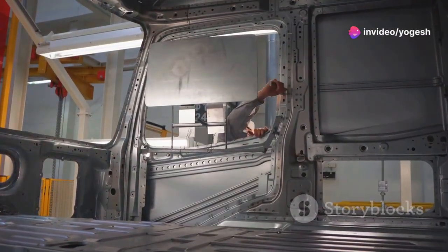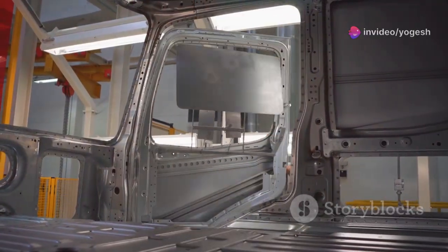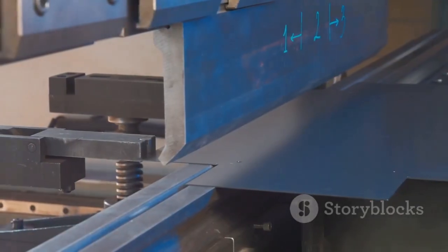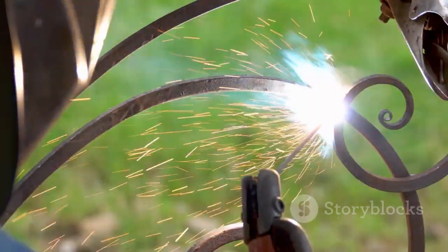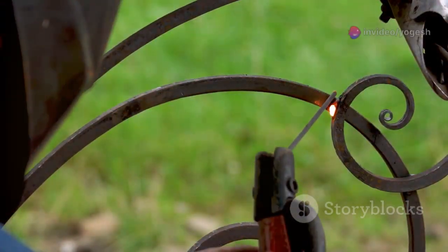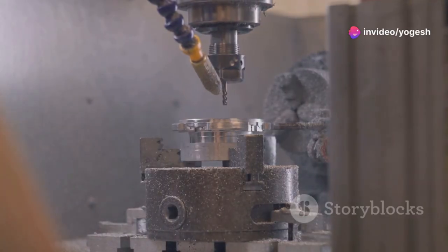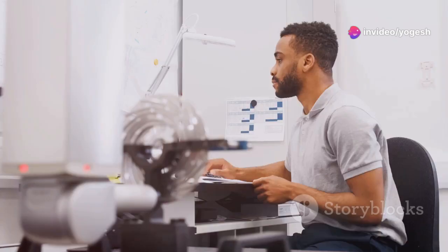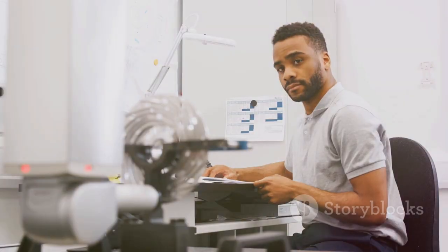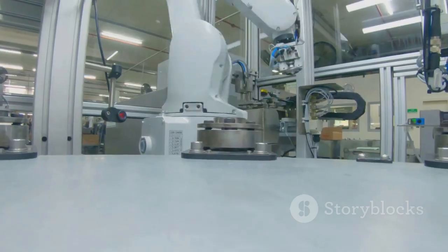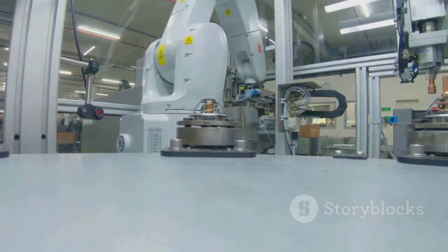Automotive and aerospace industries use them on sheet metal and composite assemblies, where entire surfaces are too flexible to serve as datums. Welded structures also rely on datum targets to compensate for distortion and ensure accurate machining of critical features. In every case, datum targets bridge the gap between imperfect parts and precise manufacturing. They're the foundation for repeatable, high-quality production.